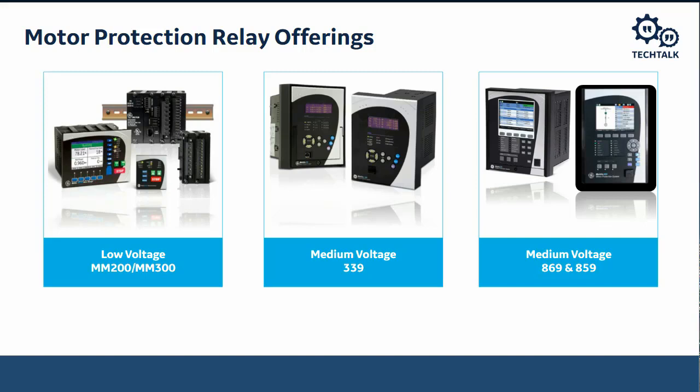That's okay because the 369 is easily replaced with an 859, which is shown on the far right. The medium voltage platforms available today that you should consider for medium voltage relays that require a lot of protection are the 859 and the 869, and especially the 859 for retrofit of the 369.